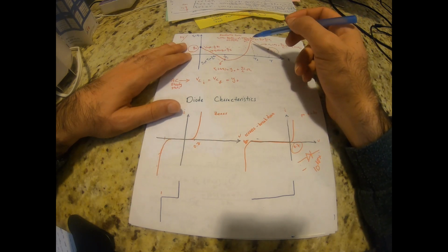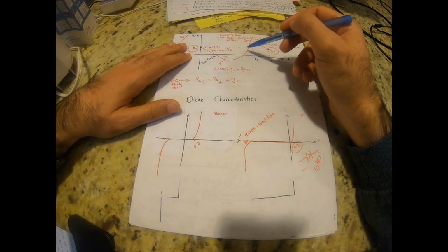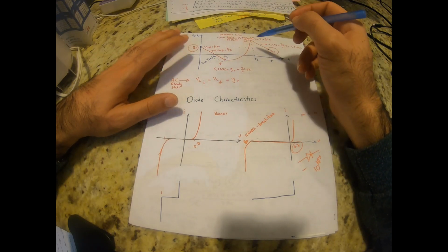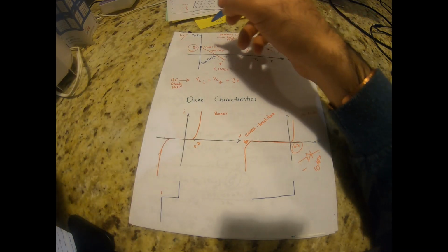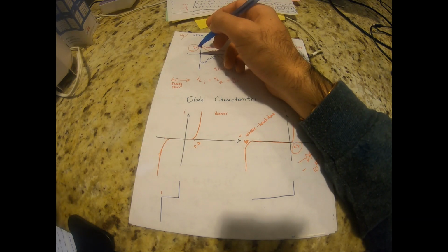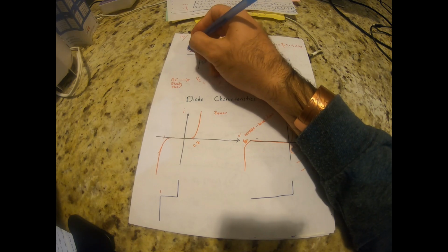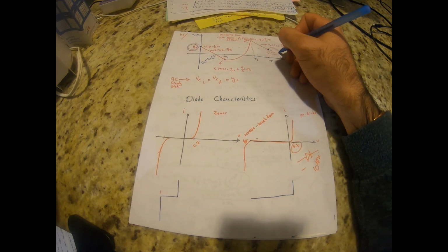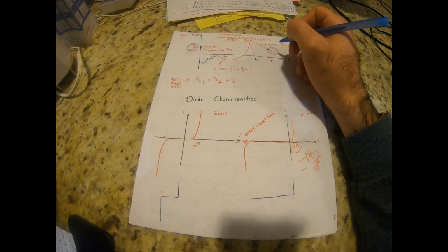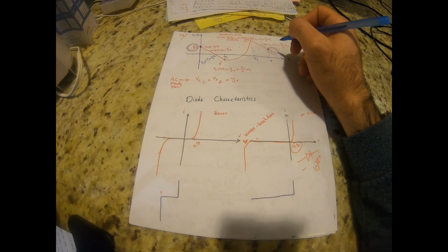You can actually change the behavior slightly. And another thing that is a result of amp-second balance is that the voltage of the capacitor at the beginning of a period is always going to be the same as at the end of the period.